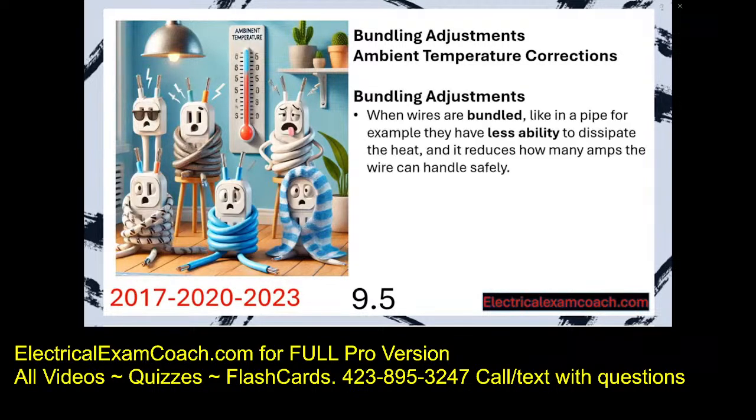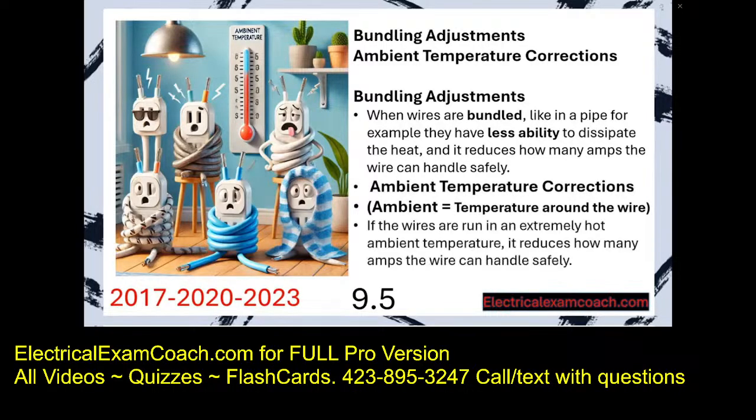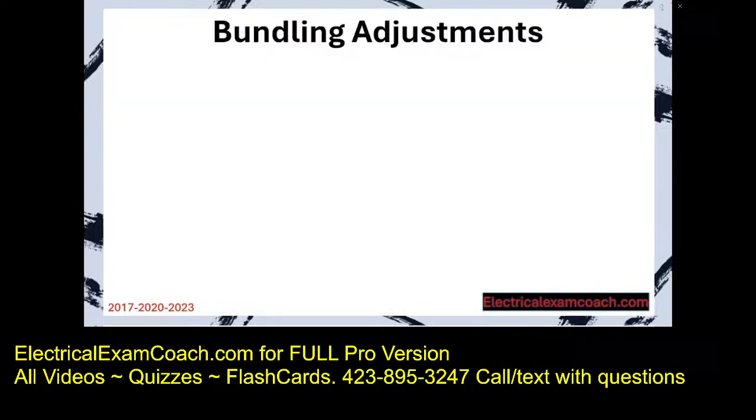Bundling adjustments work like this. When wires are bundled, like in a pipe for example, they have less ability to dissipate the heat, and it reduces how many amps the wire can handle safely. Ambient temperature corrections are like this. If wires are run in an extremely hot ambient temperature, it reduces how many amps the wire can handle safely. We're going to learn about these one at a time. Let's dive into bundling adjustments.